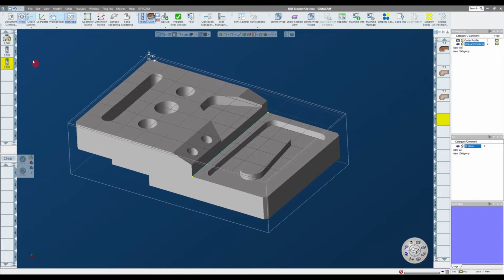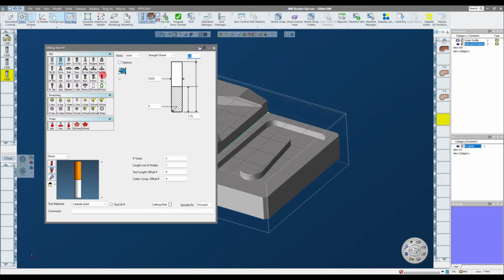So in this one, I'm going to use that same 1-inch endmill. Actually, I'll use a different one. I'll create a larger tool. I'll create a shell mill or a 90-degree insert mill. I'll call it 1.5 inches. We'll give it a 1.25 inch shank. We'll say we have 3/4 inch inserts. Oops, 3/8. And we'll also put a 30th corner radius on these as well. So 1.5 inch diameter, 90-degree insert cutter.